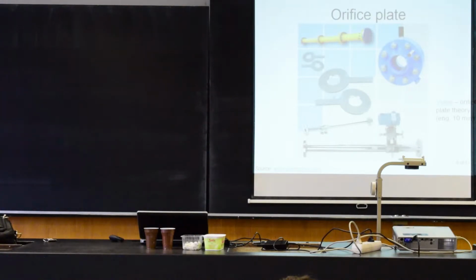You need to do the same also behind the orifice plate, but it's not that critical. So behind the orifice plate you have a quite shorter section, at least 5 pipe diameters, but in front of the orifice plate this straight pipe needs to be really long. We'll see in the next slide a table that is saying how long that needs to be.